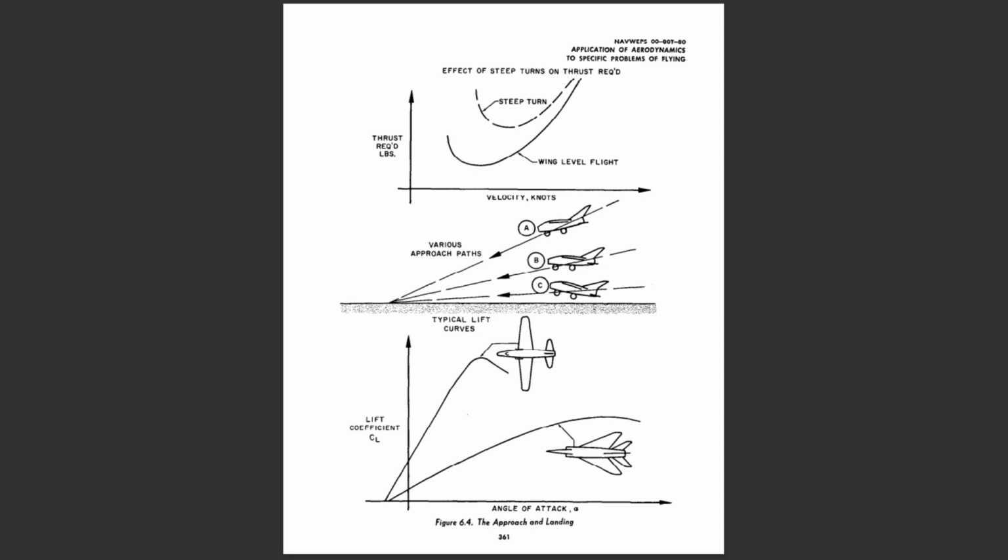The proper coordination of the controls is an absolute necessity during the approach. In this sense, due respect must be given to the primary control of airspeed and rate of descent for the conditions of the steady approach. Thus, the proper angle of attack will produce the desired approach airspeed. Too low an angle of attack will incur an excess speed, while an excessive angle of attack will produce a deficiency of speed and may cause stall or control problems. Once the proper airspeed and angle of attack are attained, the primary control of rate of descent during the steady approach will be the power setting.